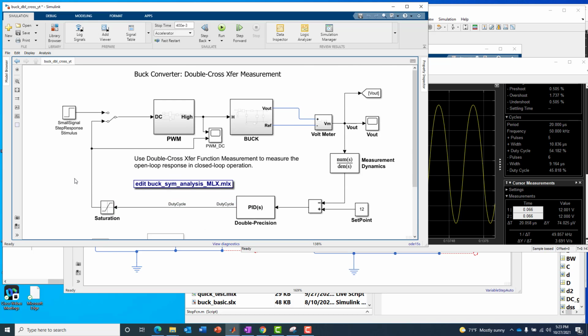Now you might ask, well, why not just monitor the signal at the duty cycle input here, monitor the signal that we've measured across the load resistor, which we just got a go-to tag on now? Monitor these two signals, perhaps take an FFT of them like we did before with our cross-spectrum, auto-spectrum based measurements, and then compute a transfer function from that. In other words, just let it run in normal closed loop operation and just log the signals, take FFTs, and compute a transfer function. It turns out, in this case, that's a little too simple and it doesn't work because this signal and this signal are very narrow band.